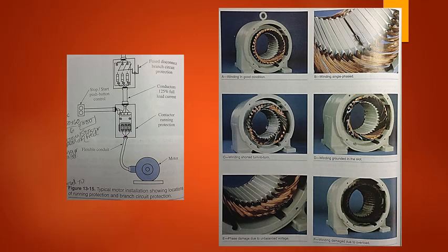Excessive bearing wear. The most common cause of motor failure is excessive bearing wear. Some bearings are sealed and do not require maintenance, while others require periodic lubrication. Dry motor bearings cause friction, heat up, and wear down rapidly.